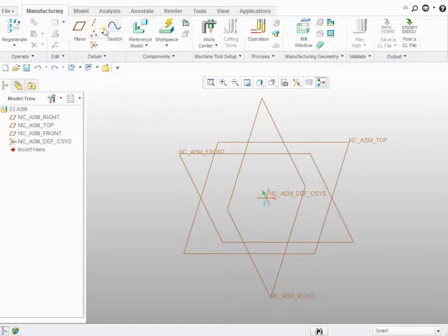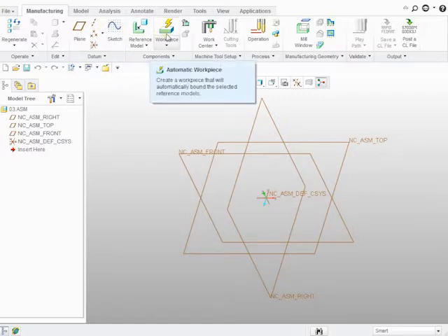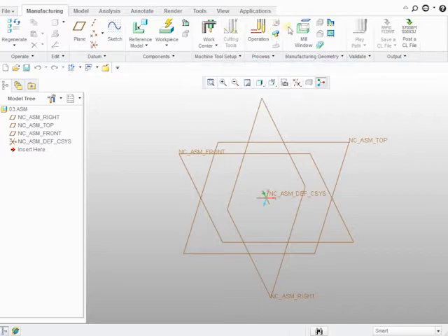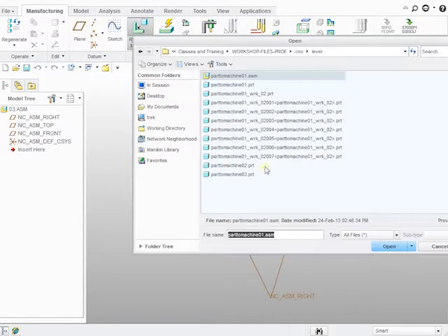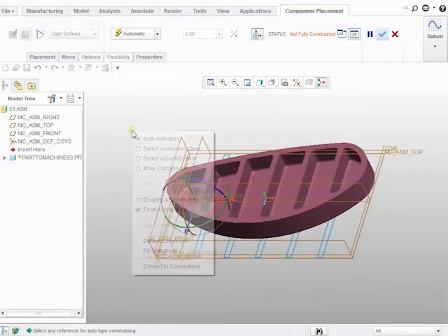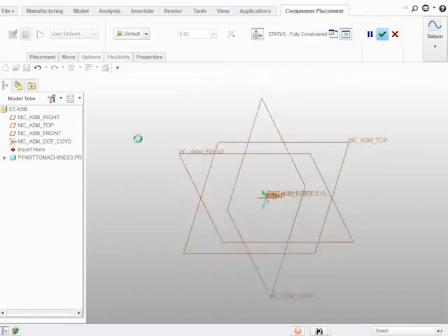First thing I need to do is talk a little bit about the user interface in Creo and how interesting it is that they've built the workflow in a direction. So first thing I need to do is build a reference model, and everything I do is in order. So let's do the reference model first, the model that I want to CNC. Right hold down, default constraint.